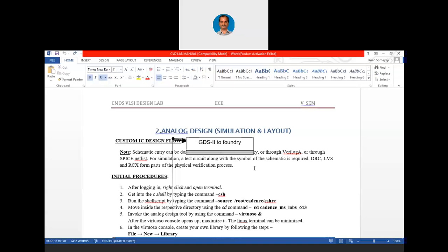Now, it is possible that without the test circuit also you can directly test, using a single circuit diagram. For that circuit diagram itself, you can give the input signal and you can plot the output. That is possible. Still, we go for a method where initially we will have a main circuit diagram. Later on, we create a symbol for that, and using the symbol, later on, we create a test circuit diagram.